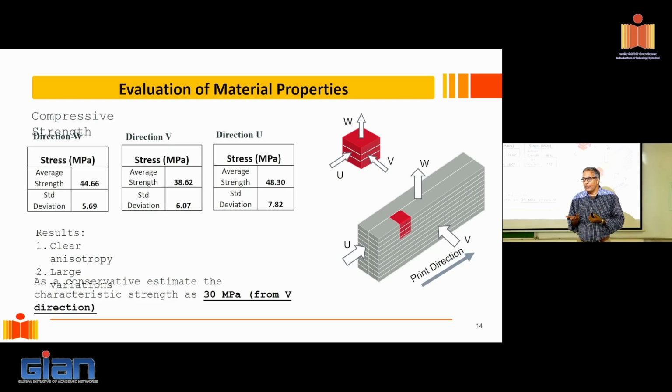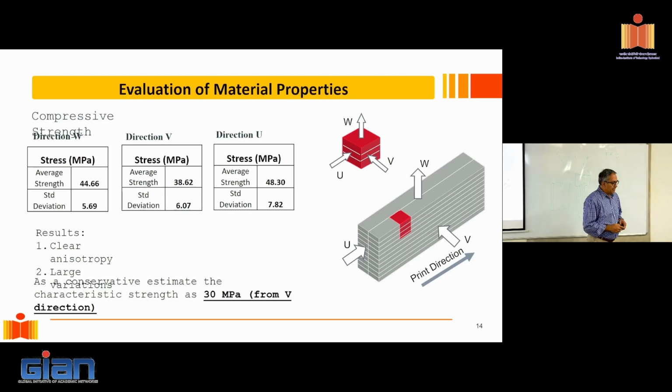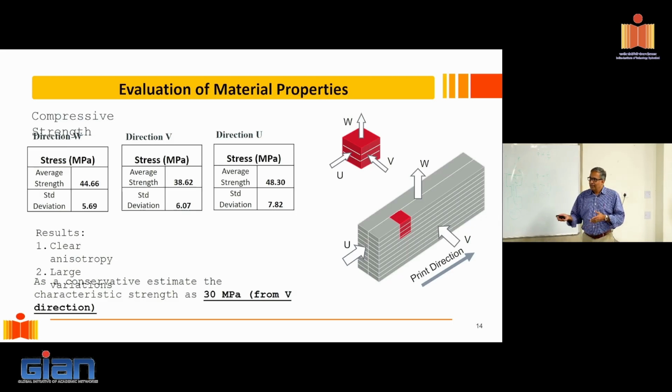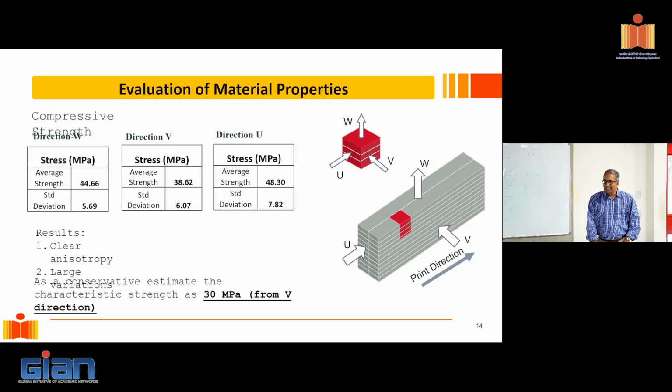That's the engineer's way of doing it, where we say, fine, I know that I have three different strengths. I'll take the lowest strength in the weakest direction and pretend as if the concrete is the same strength in all directions. Right? So that's how we actually started, when we said, okay, when we have to do the design, let's do this. Later on, I'll show you that that is not exactly the best way to do it. There are other things we need to consider. This engineer's way of thinking has to be refined.